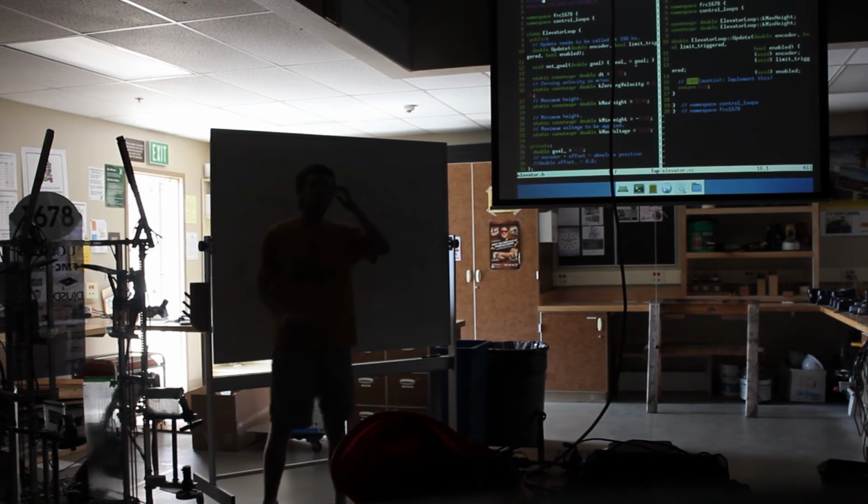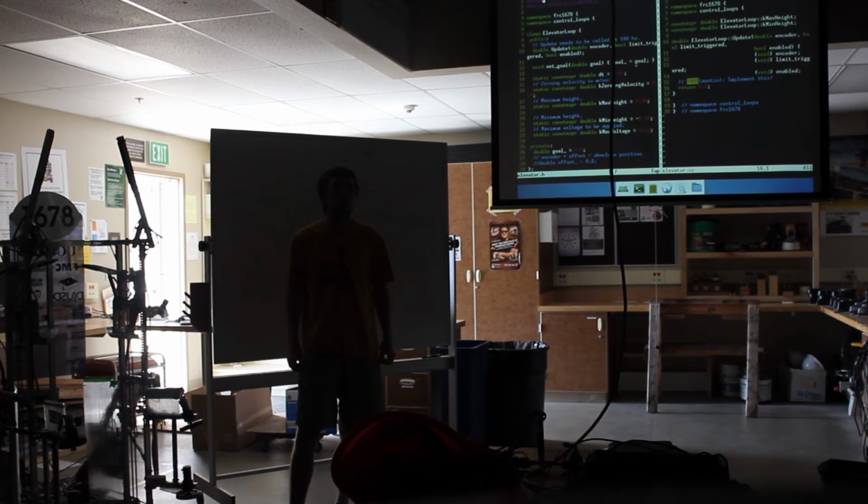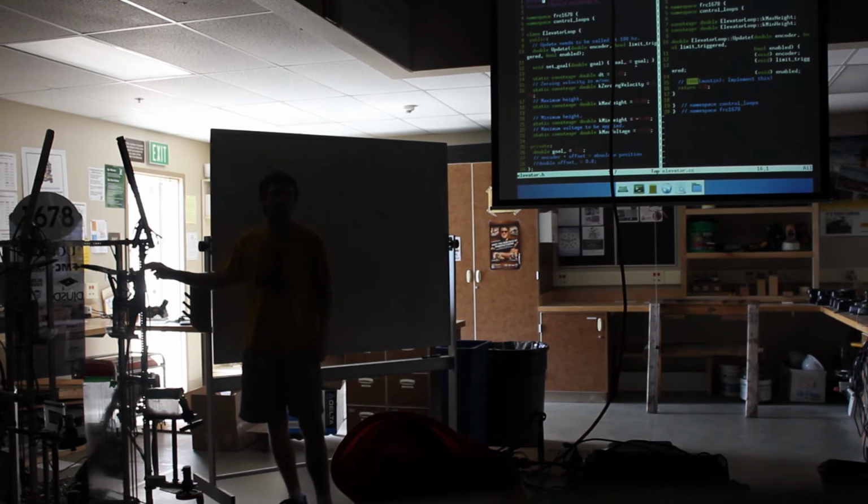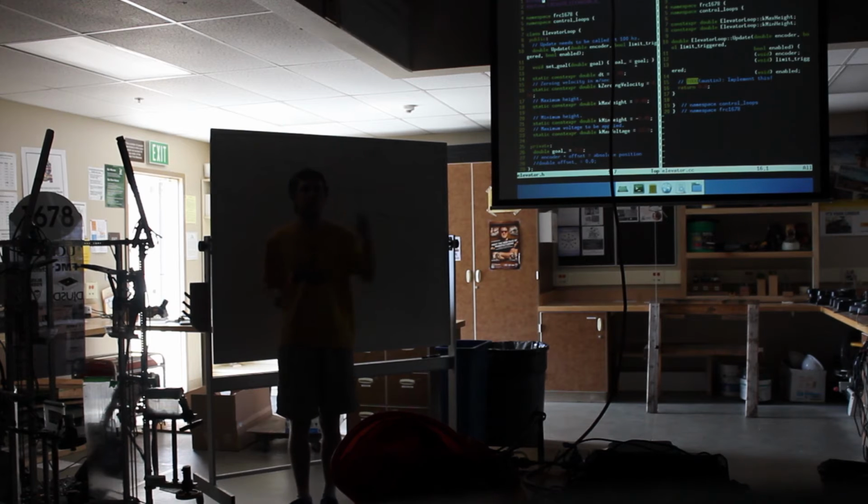When you're trying to zero it, why do you care where you started? You say you're trying to determine the offset? Yes, we care because the encoder is going to read out 0 up here, and we want to know how to convert encoder units to real units. So the way to do that is you move till you find 0, and then you look at what the encoder read at that point, which will be the distance from where you started, and then you subtract that out all the time, and then you're good.